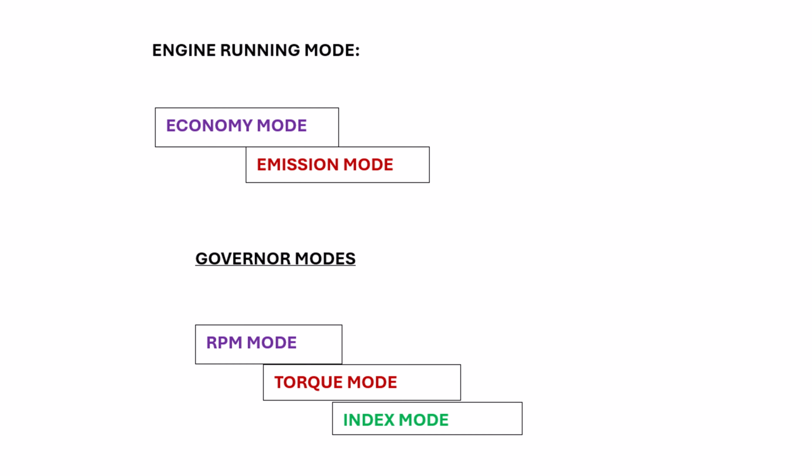If RPM has dropped to 79, and the amount of fuel which the top limiter allows can be released and RPM can reach 80, then it's all right. Otherwise, if it cannot, RPM will remain at 79. So the advantage of using torque mode is the engine never gets overloaded. So the RPM will vary, but torque index will be kept in a certain range.